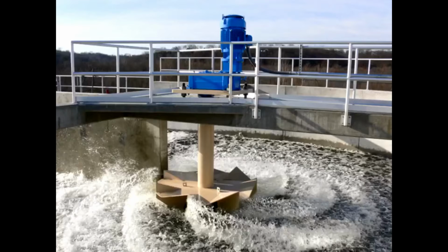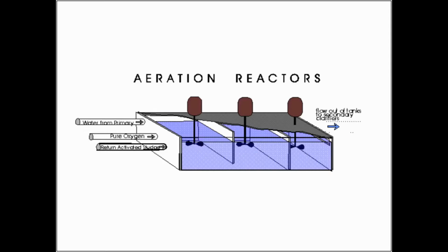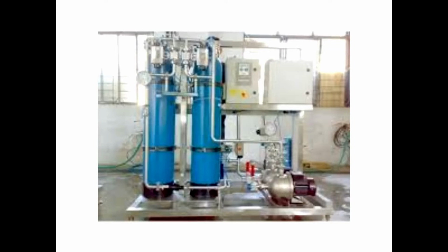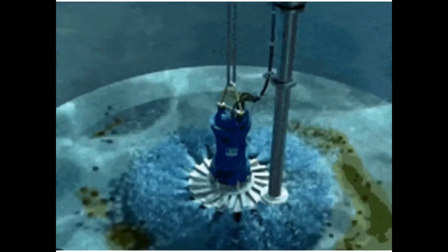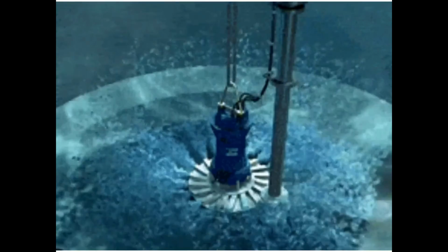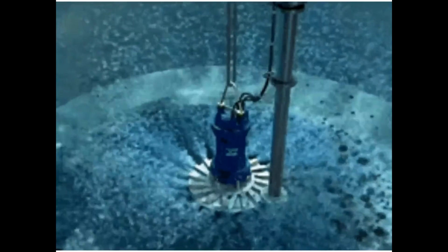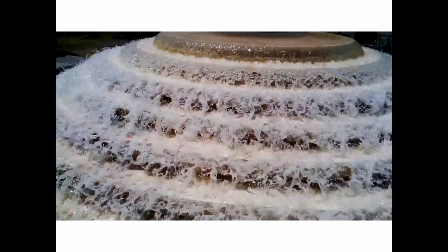Step 4. Aeration or activated sludge. In this step, the wastewater receives most of its treatment. Through biological degradation, the pollutants are consumed by microorganisms and transformed into cell tissue, water and nitrogen. The biological activity occurring in this step is very similar to what occurs at the bottom of lakes and rivers. But in these areas, the degradation takes years to accomplish.